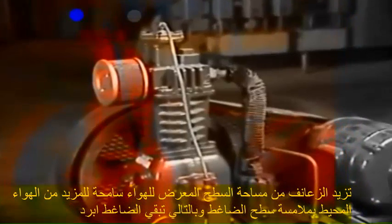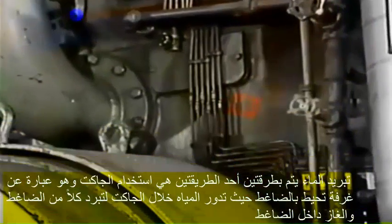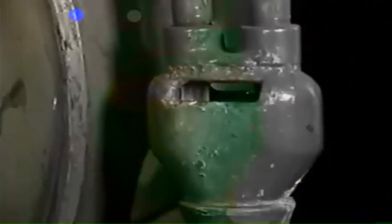An air-cooled compressor is easily identified by metal fins on its casing. The fins provide increased surface area, allowing more of the surrounding air to come in contact with the casing and therefore keep the compressor cooler. Water cooling can be accomplished in two ways. One way is to use jackets. A jacket is a chamber that surrounds the compressor. Water is circulated through the jacket to cool both the compressor and the gas inside it.